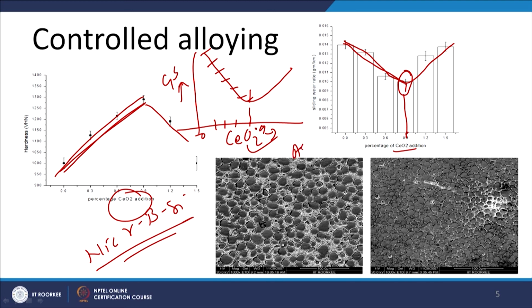This is the as-sprayed flame spray coating of the nickel, chromium, boron, silicon material, where the average diameter of the nickel solid solution cells is coarser as compared to the other case where the nickel solid solution cells are finer, under identical conditions of scale. This kind of refinement is attributed to the heterogeneous nucleation being promoted by the favorable alloying elements.